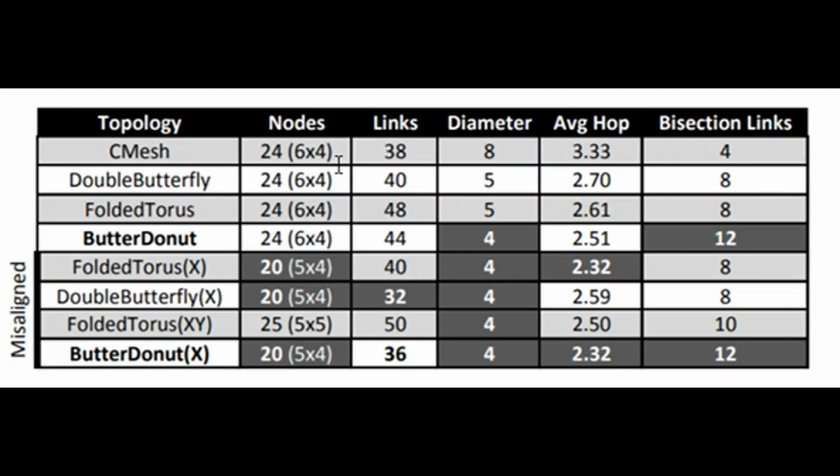The number of nodes would simply be the number of routers. Generally speaking, the fewer of these the better, as these are of course active transistors using up a little power. The fewer links and the lower the diameter of the links the better, and those should combine to an average number of hops. And the more bisectional links, the better the chip-to-chip, side-to-side communication should be.